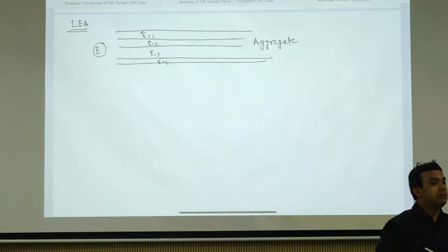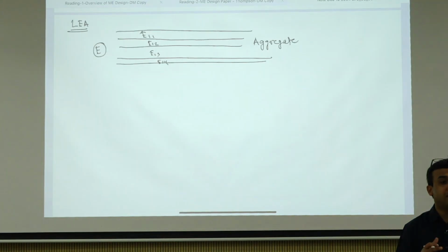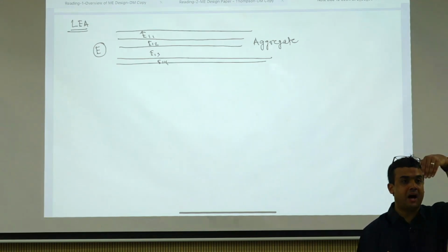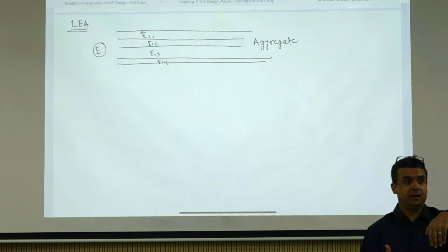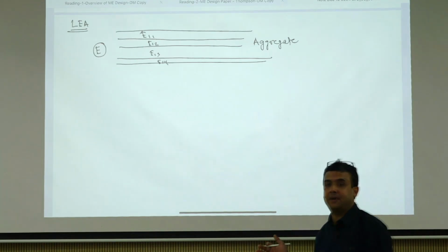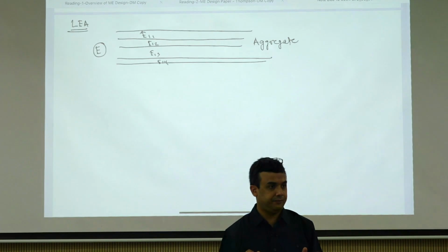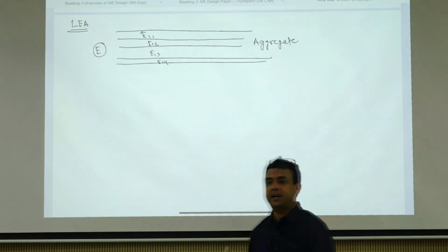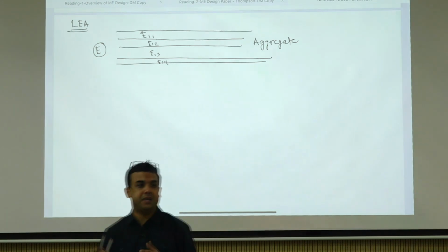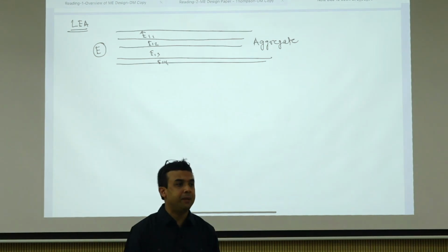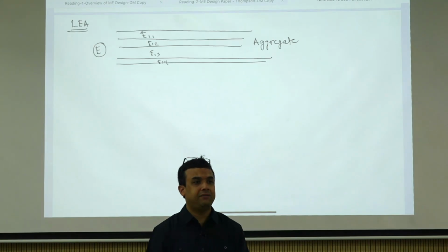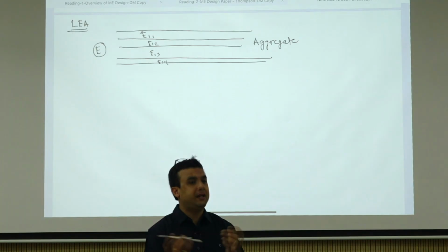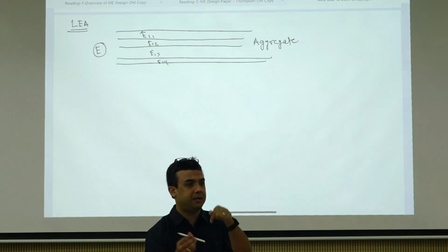Then the question comes: yesterday I told you something called anisotropy as well, right? Standard finite element codes cannot capture that. There are special finite element codes. One was actually developed by my PhD advisor. It's called GT-PAVE, or Georgia Tech PAVE. It's not public anymore, but there you had the ability to model anisotropic layer behavior as well.